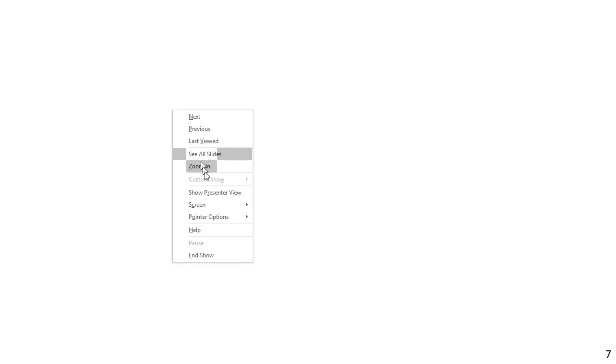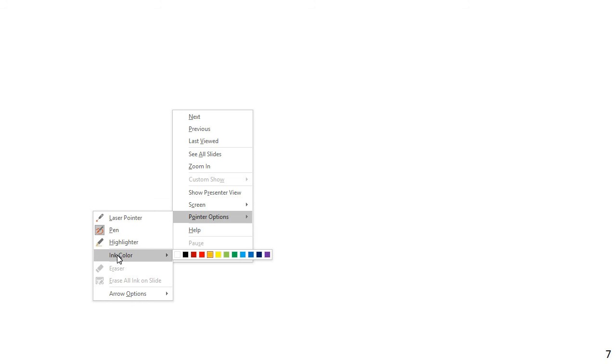Okay, so what I'm going to do next is draw this frame out and find its shear and bending moment diagrams via the method of inspection, or by inspection. Because again, once we have the member end forces, we can figure out the rest fairly easily. The whole point of finding the member end forces is that you can then isolate and analyze each individual beam and column as an isolated object. And once you know the end forces, you can get the shear and bending moment diagrams fairly quickly, or fairly easily. Well, relatively easily.